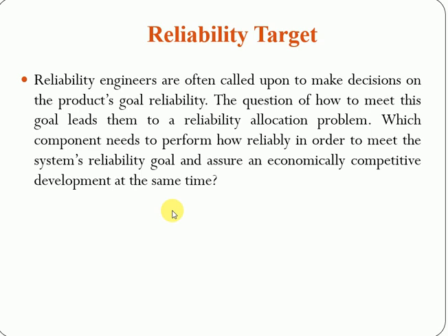Here we are discussing some methods: Selinov, Churchman, Werner. The approach by Selinov considers the total cost of a technical product over its useful life, and herein includes investment cost, cost proportional to the operating time, as well as cost increasing with operation time, which is maintenance cost.